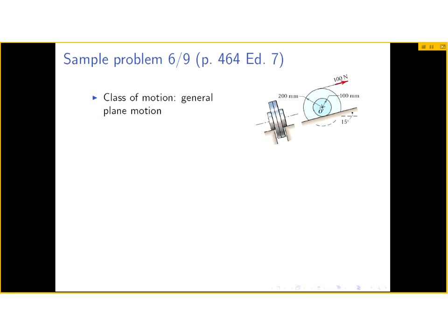The only exception would be if you can clearly see that you can derive an expression for the angular acceleration alpha in terms of the angle theta, in which case you can use the omega d omega equals alpha d theta type of integration, as allowed by equation 5.1. So in this case, we have this problem.